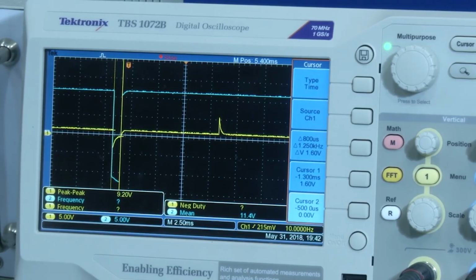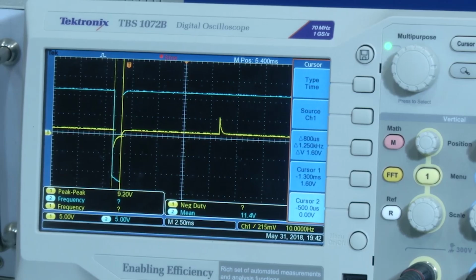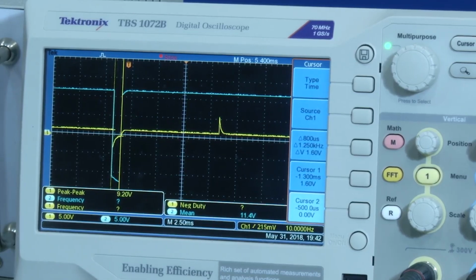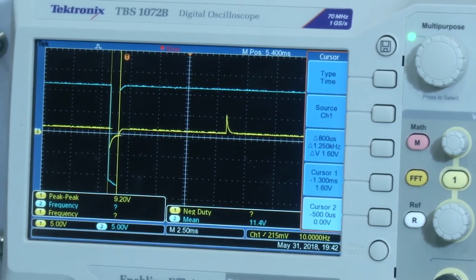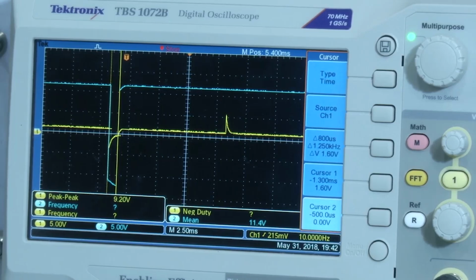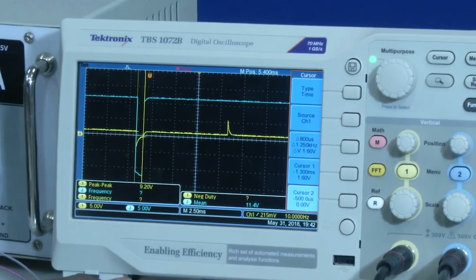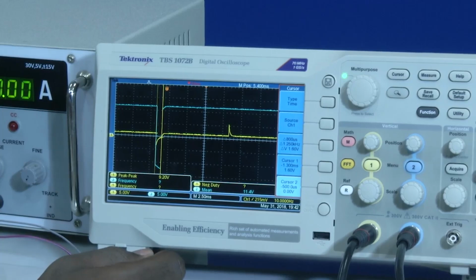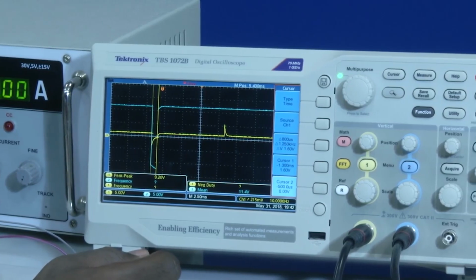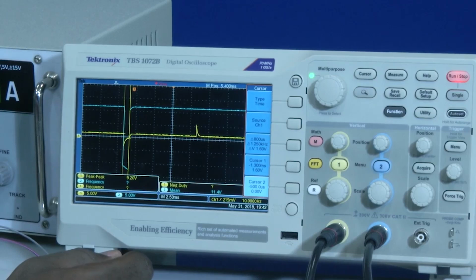So, that means we can understand that in order to generate a triggering pulse for a monostable multivibrator, until we generate a triggering pulse, we cannot see any change in our output because of our diode, which makes the capacitor stay at 0.7 volts, which will not allow the capacitor to charge more than that. Since it cannot charge, the voltage at VA, which is nothing but the negative terminal, is smaller than that of the higher threshold value. As a result, the output will always stay at plus VCC, right.